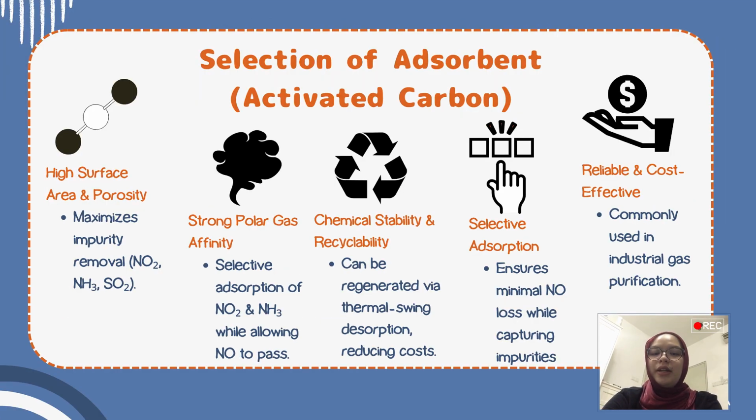Selection of adsorbent. Activated carbon was chosen as the primary adsorbent for its exceptional ability to capture impurities. With a large surface area and a high porosity, it efficiently removes NO2, NH3 and SO2. Its strong affinity for polar gases ensures selective adsorption while allowing NO to pass through.